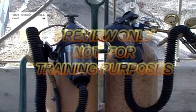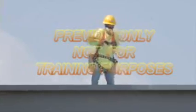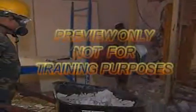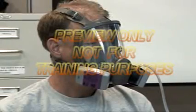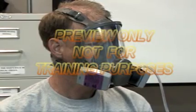When effective control measures are not feasible or while they are being instituted, appropriate respirators must be used. OSHA considers respirators to be the least effective means of exposure control for the following reasons. Respirators only protect if properly fitted and worn during the job. Respirators only protect the employee wearing the respirator and not the whole workplace. Respirators are uncomfortable to wear, difficult to use, and make communication difficult. The cost, which includes medical examinations, fit testing, training, and purchasing, can be very expensive.